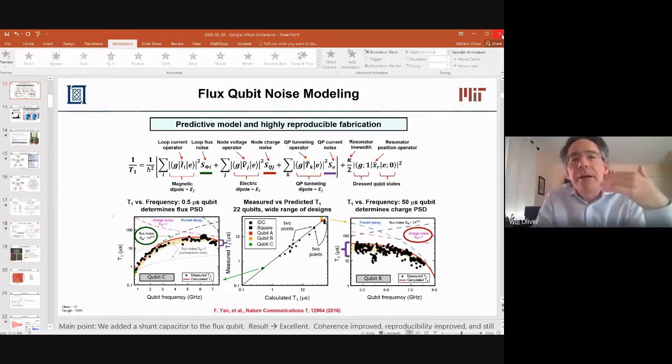Yeah, that's right. So anytime we want to change the qubit frequency of a composite qubit, we have to simultaneously apply flux biases to both underlying transmons. And that's 2 transmons per composite qubit. So if we do coupled composite qubits, we're actually simultaneously biasing 4 underlying transmons.